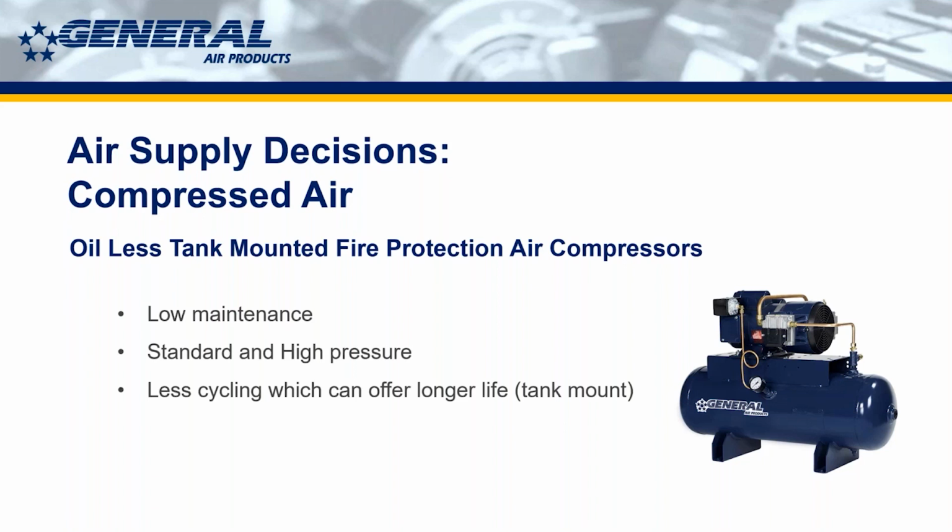A tank-mounted air compressor with an air maintenance device is, to me, what should be on every dry valve and every pre-action valve, if possible. And then lubricated or oilless based off of what we were talking about before, who's going to do maintenance and such.